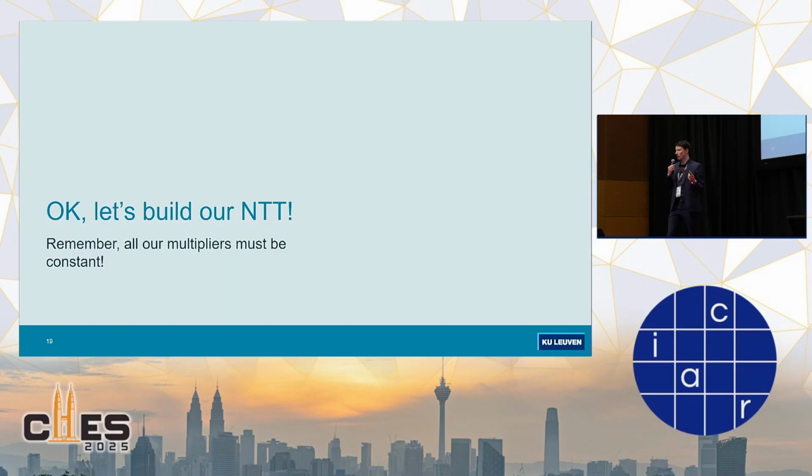And now people who are hardware designers might already be saying, well, okay, this is ridiculous. Sure, if you could do constant multiplies, this would be fair, but you can't do constant multiplies because you have butterfly circuits and you have to feed in the twiddle factor, and that twiddle factor changes.